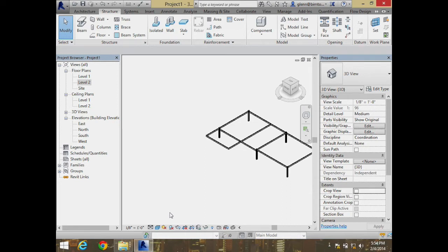So what's happening here is we're saying the one going left to right is actually carrying the load as a simply supported load back to these 2 columns, and then this is coming down as a point load in the middle of that beam. So it's supporting that. One's just got to dominate. Another way to do it, though, a perfectly valid way, would have been to put a column right here. And then that would have supported this one cantilevered out in the same way. So, different choices. It's kind of tricky in terms of thinking about that.